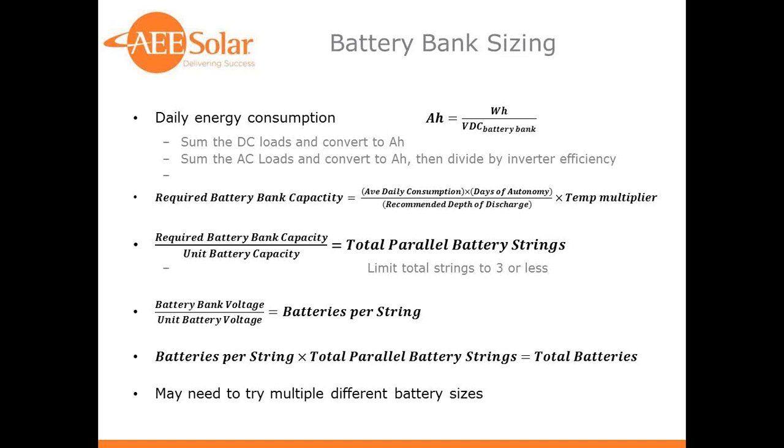And when you're sizing a system, you may need to try multiple different battery sizes. Maybe take a look at L16s, take a look at a larger battery, maybe look at some sealed batteries. Depending on the application, depending on your customer's needs, and the cost of batteries, you're going to want to compare several different scenarios and see what's the best for the application.